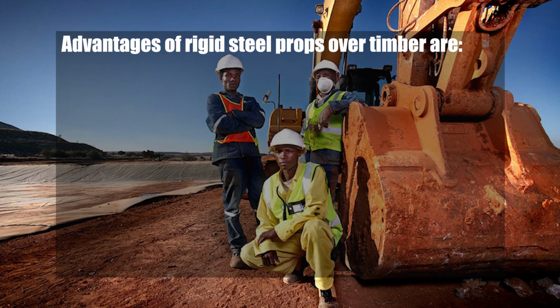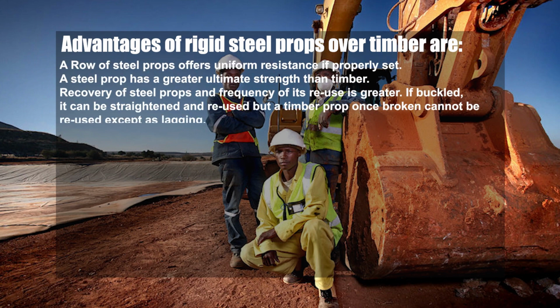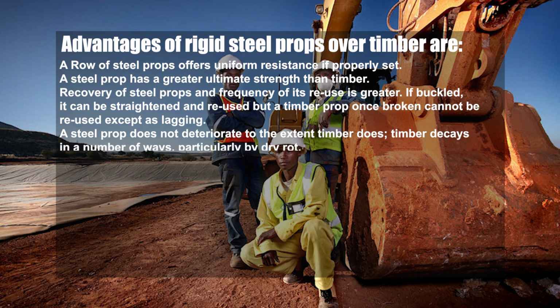Advantages of rigid steel props over timber are: first, a row of steel props offers uniform resistance if properly set. Second, a steel prop has a greater ultimate strength than timber. Third, recovery of steel props and frequency of their reuse is greater.